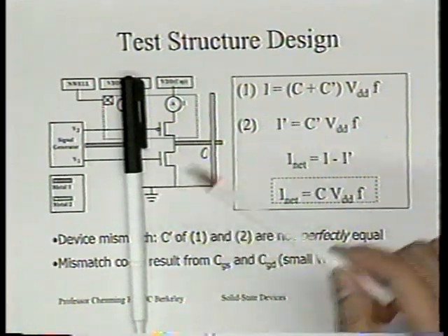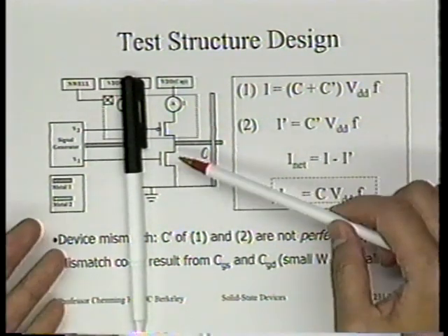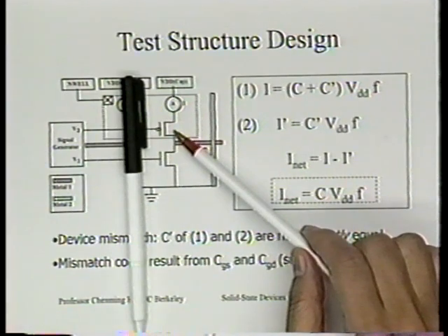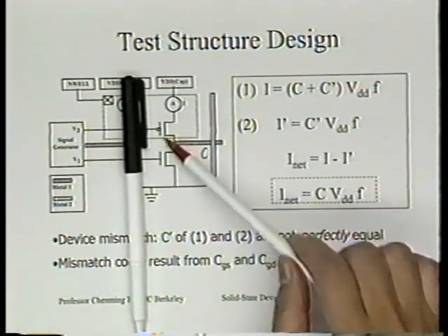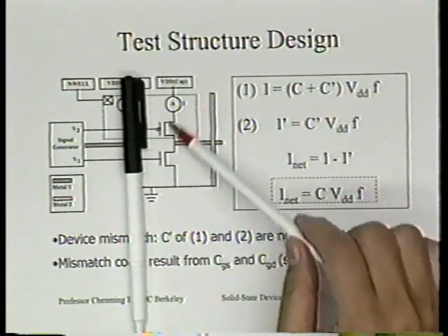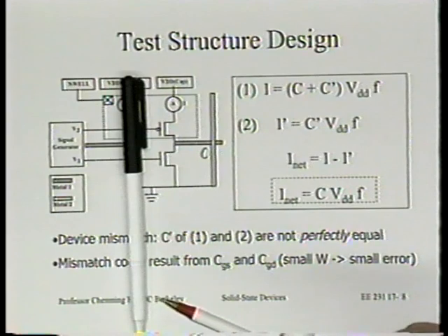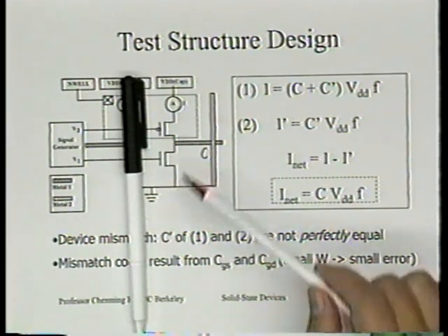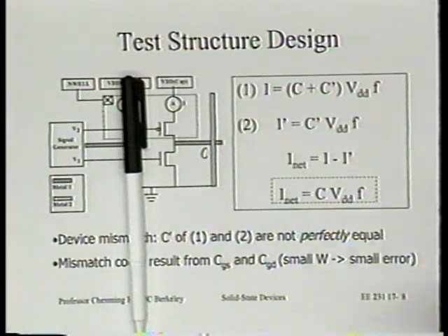After a while, so that there's no short circuit current, we repeat the process. We turn on the P-channel transistor again. So what we're doing is kind of a charge pump circuit. We pump charge into this load and then dump it. In this case, what will the DC ammeter read? Let's think about it. What does the DC ammeter read?